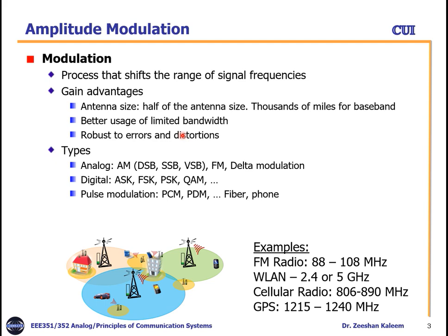How is the bandwidth usage better? Whenever we generate a signal in the low frequencies, every signal is usually generated in that same particular band. So by doing modulation, we can use the higher frequency bands as well. Another benefit is that it is robust to errors and distortions.